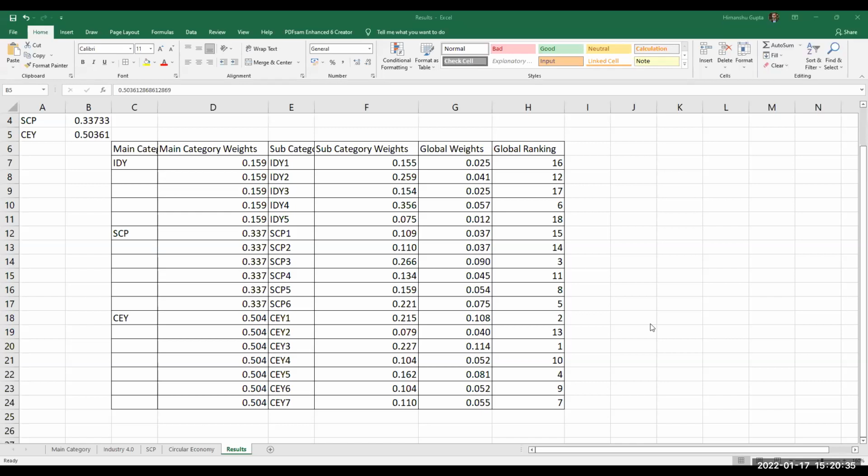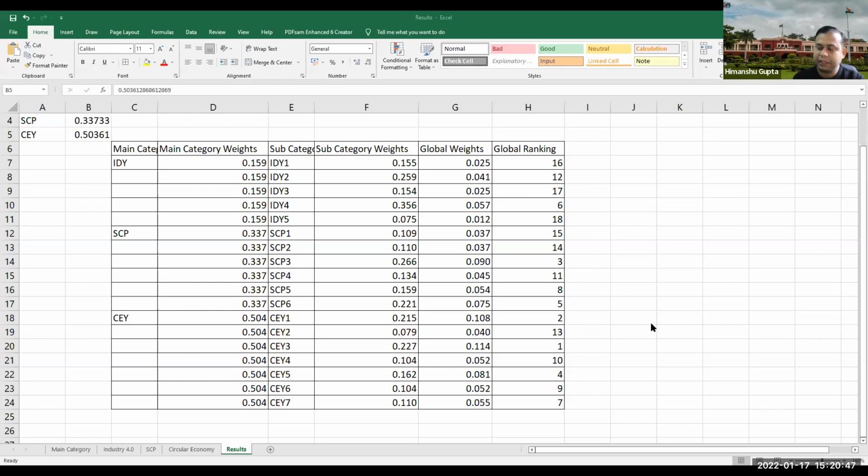Yeah, design of experiments, I think, is relevant to Taguchi methodology, where they select an L9 or L19 orthogonal array for experimentation. Yes. The basis is basically ANOVA. We are comparing the means of the different settings that we have made for our experiment, seeing whether there is a difference in mean value between those settings, and that will help us decide which one is the most optimal for us.